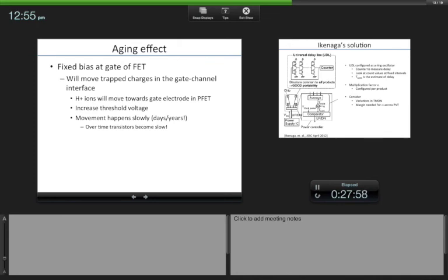In the case of a transistor, what happens, right? So again, equivalently you have to see what are the physical mechanisms which are changing the characteristic of the transistor. So one of them is that, essentially it has got to do with the oxide, right? You can start degrading the oxide, perhaps due to various reasons. With heavy electric fields, you start creating punctures in the oxide, and then it's no longer as insulating as it should be. Another thing, which has this acronym BTI, bias temperature instability, right? So it is either NBTI, negative bias temperature instability for PMOSes, or PBTI, positive bias temperature instability for NMOSes.